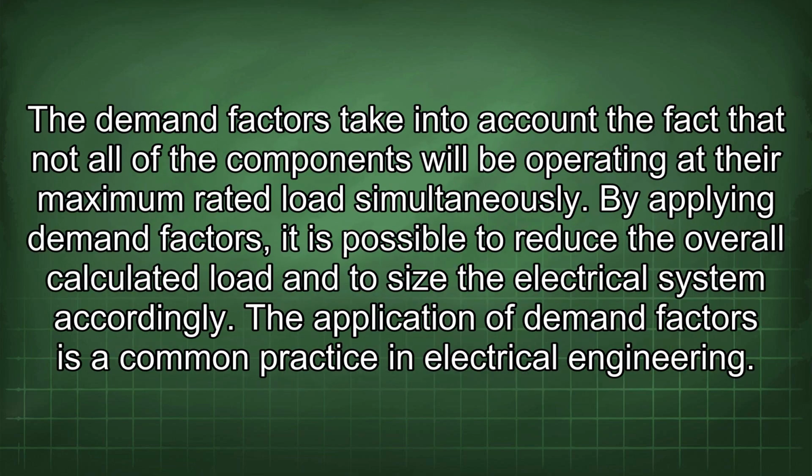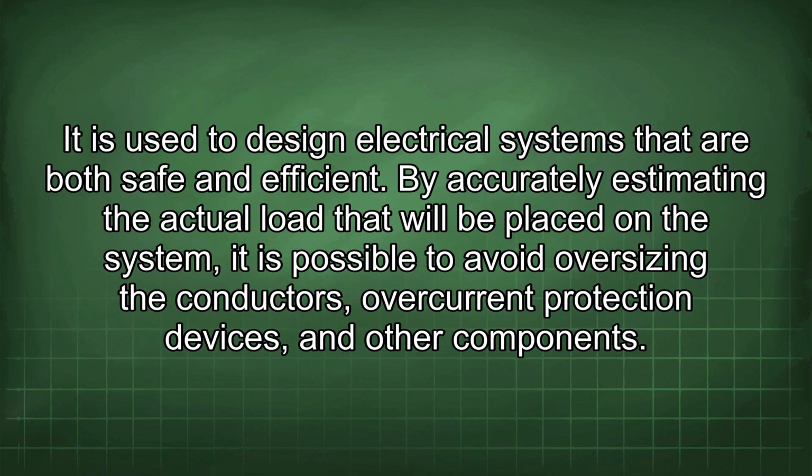The demand factors take into account the fact that not all of the components will be operating at the maximum rated load simultaneously. By applying demand factors, it is possible to reduce the overall calculated load and to size the electrical system accordingly. The application of demand factors is a common practice in electrical engineering. It is used to design electrical systems that are both safe and efficient.